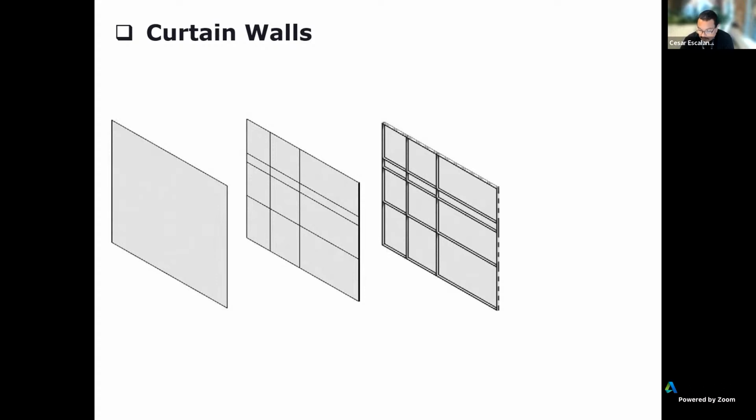If you look at the shop drawings of curtain wall profiles, you can see that they may have slight variations, and you can be as detailed as needed to display a specific profile. Then you can place interior mullions in the horizontal, interior mullions in the vertical, and sill and jamb mullions with different profiles. This is a manual method, so it's more time consuming.